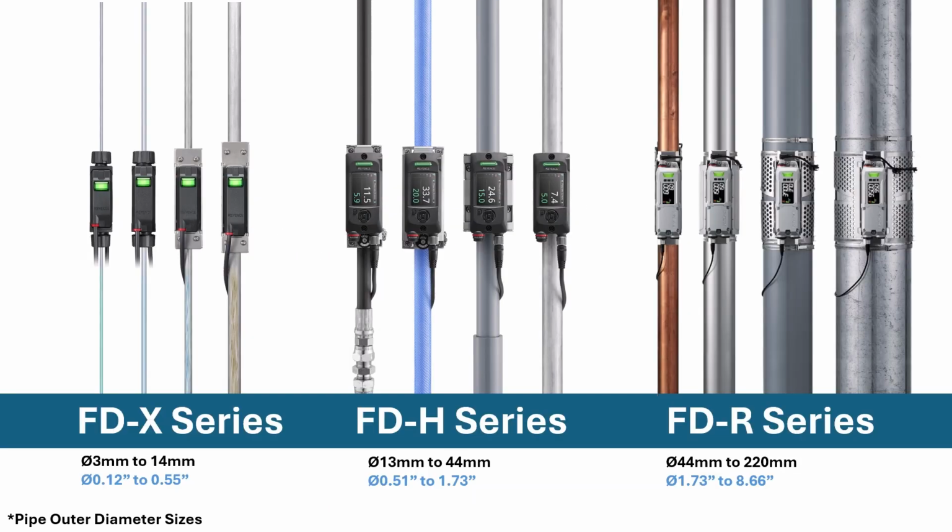Now that we understand what stability is and how to achieve it, utilize the stability bars on the flow meter to confirm that the flow meter is mounted in a good spot and detecting properly.